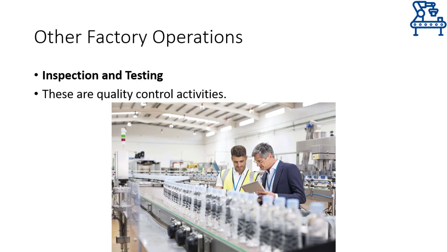The third operation going on in a plant is testing and inspection. This operation acts as the feedback for the quality of the products the manufacturing plant is producing. Sometimes online inspection is performed, that is, parts are being monitored and tested for quality while they are being manufactured, whereas sometimes the inspection is done once the part has been completed. Online inspection although requires more resources, but it can help in saving valuable time. A certain low quality part is rejected right away instead of waiting for it to be completed and then checking only to reject it at the end. Normally, systems are incorporated in the manufacturing line that keep a check on the defined part parameters.